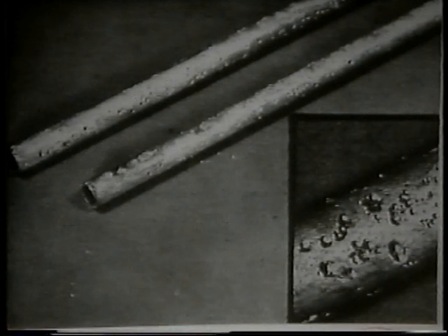In fact, we find that stagnant seawater is much more corrosive for the stainless steels and those materials that depend upon passivity than is flowing seawater. The common corrosion control technology for stainless steel piping is to maintain the flow of water through the piping system continually, or else to shut down and drain the system in times of shutdown.